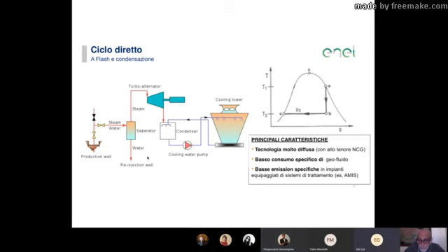Professor? Yes. What if we use a double stage or two-stage steam turbine, so we can increase the efficiency of electricity? Yes. I'm not going to show you this, but you can also have a two-stage, and since the water that comes in the separator as it enters the power plant is at very high pressure, usually 20 bar, then you can have a second stage of vaporization at low pressure, say at 5 bars, and then this vapor, you run it again through a second turbine.